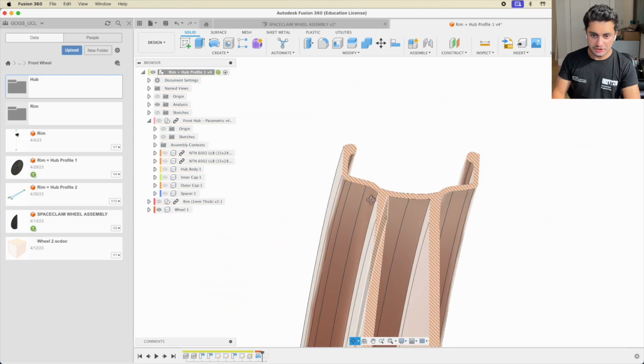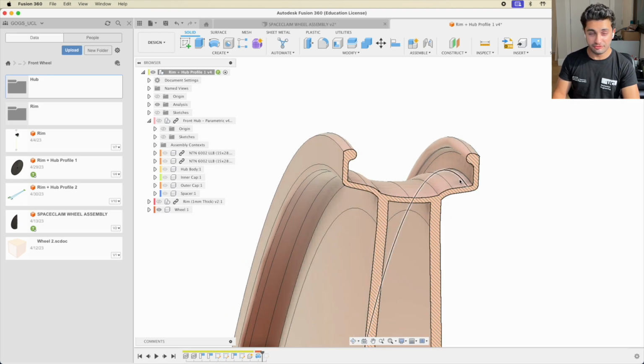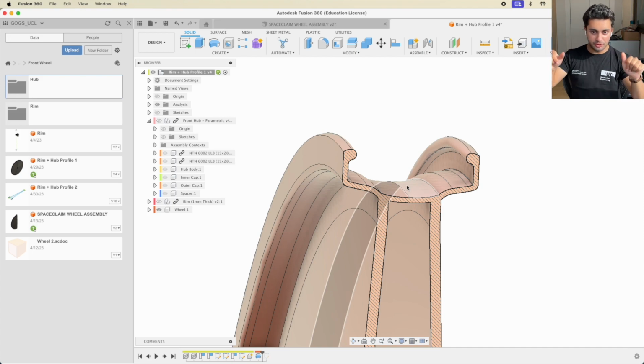Now, I told you this will be a minimum viable product design, in that we're going to use the simulations to optimize that initial design by actually removing material around the wheel. So that is the way a structural optimization algorithm works. It starts with a blank billet, you could call it, the design that occupies the maximum possible volume that you could ever conceive the wheel occupying.